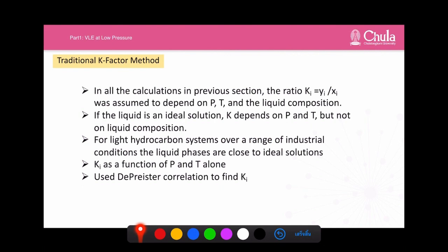Okay, so well, now we discuss again the K-factor method for the calculation. Well, in an ideal solution system, for example a hydrocarbon system, you can use the K-factor method for the VLE calculation, where K is the ratio of y and x, right?